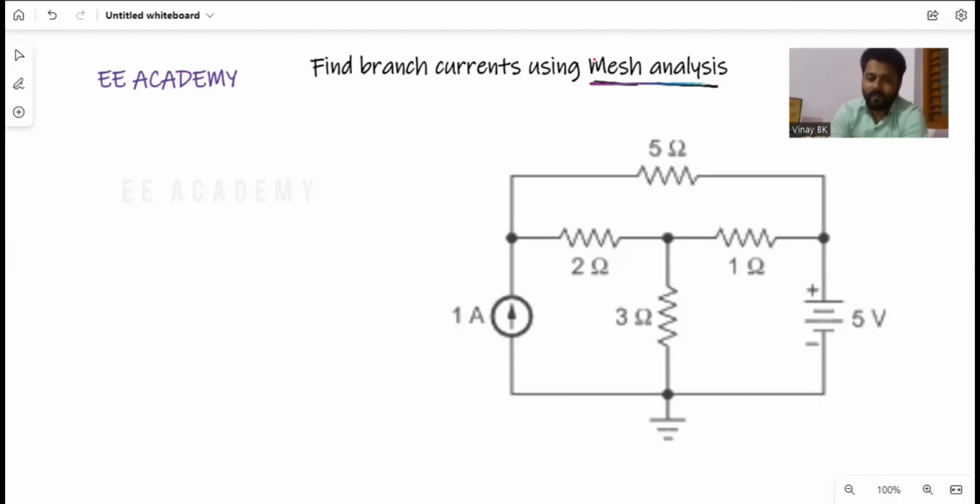So first step, as I told, I'm naming the nodes here. There are nodes A, B, C, D, E, F, G, H. There is a current flowing from H to A, which you just neglect. First you write the letters or namings. After that, give loop direction along with the current.